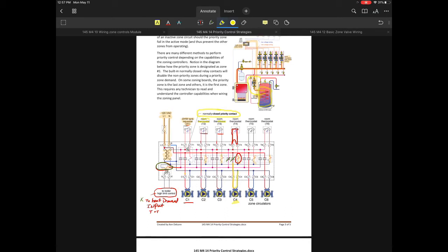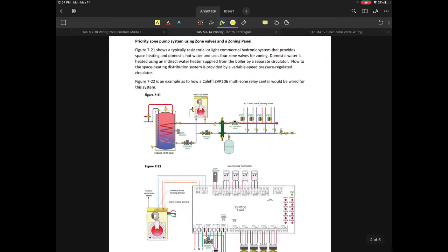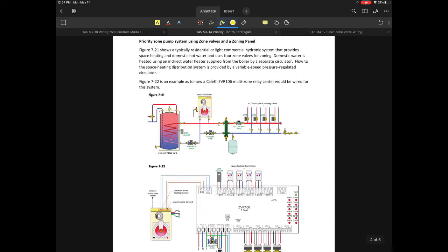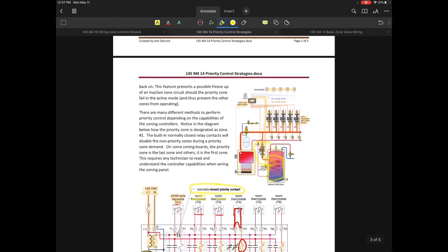It makes the job much, much easier. So when I said earlier, in the long run, I think in a lot of ways a customer would be better off. They would actually save money in the long run, purely from a troubleshooting standpoint later on down the road. I can go to a zoning panel, I can see everything brought right back to one spot, and I don't have to sift through a bunch of wire nuts trying to figure out what happened here and what happened there. So it's a much nicer setup.